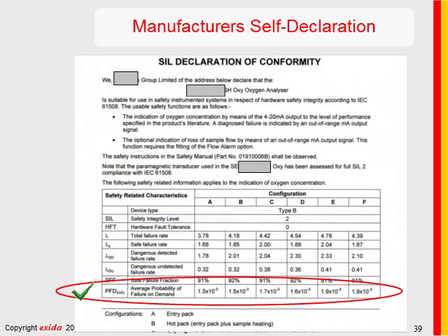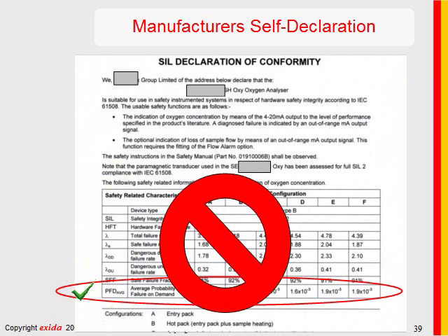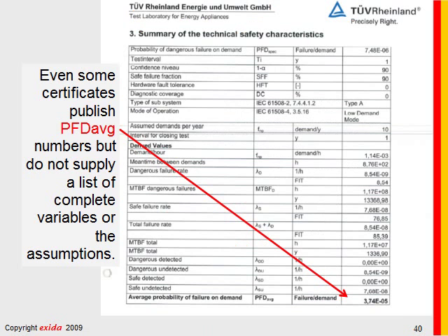There was an incident, and actually the engineer blamed it on the PFD number in the report, not on their own SIF verification. I don't like publishing PFDavg numbers, and I don't like to see them published when they will mislead people into designing poor safety systems. Even some certification bodies publish PFDavg numbers on the certificates.